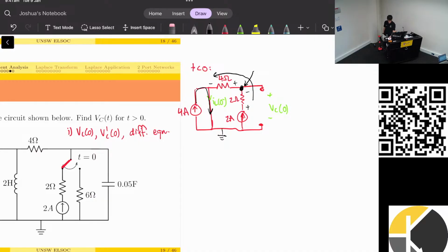The 2 ohms. So if we use the 2 ohms, we can get the voltage here and here, but we don't know the voltage across the current source, right? So that kind of leaves us at a problem because we want to find the voltage from this node to this node. If we use the 4 ohms instead, since this node is the same because it's short-circuited, and this is also ground, so the voltage across the 4 ohms is actually the same as the voltage across the capacitor.